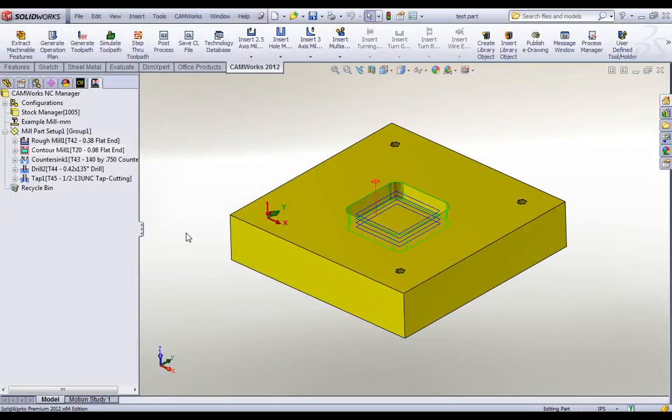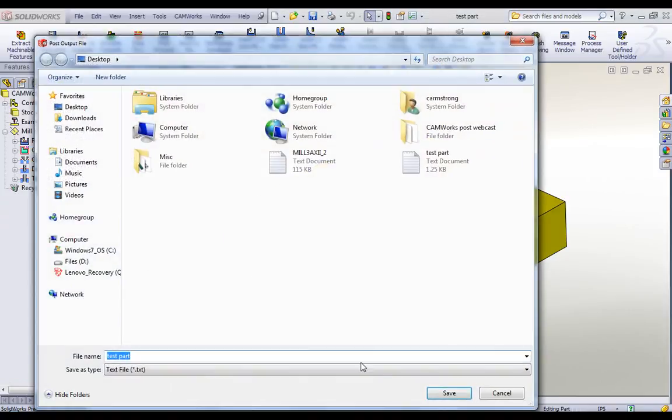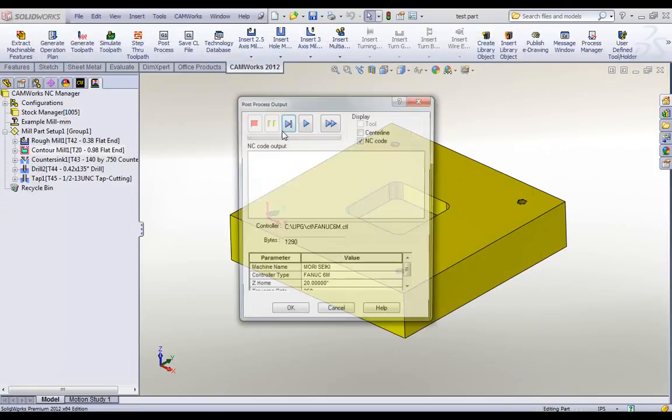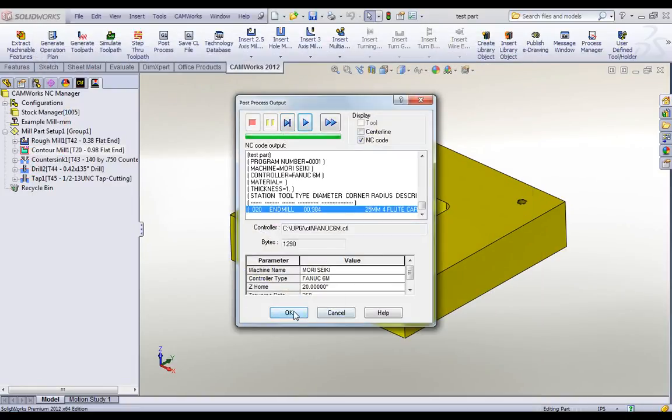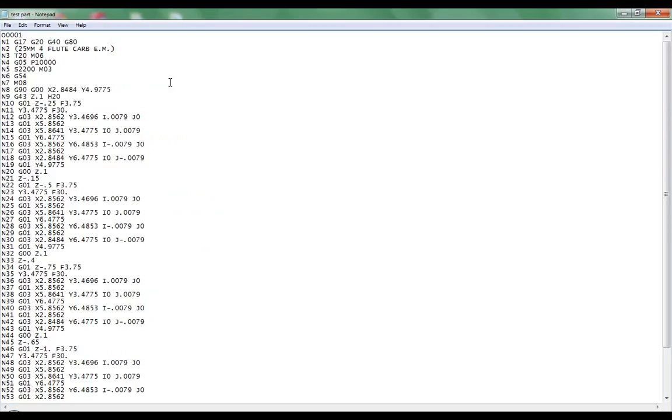Now if you remember, there was nothing between the tool change command, T whatever M6, and my spindle command. Now if I did this right, it should show up right between those two. So I'm going to go ahead and say yes, and we'll take a look at that. And so now you'll notice between the tool change command and the spindle command is my G5 P10,000. Okay, and so that's really what I've accomplished here.